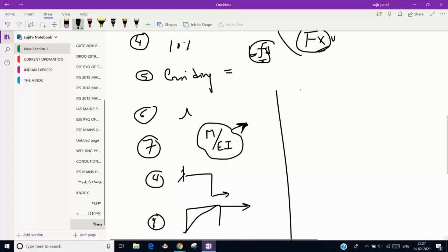Moving to the next question. There is one question on the application of friction: the angle theta is 30 degrees, and one block has a 900 Newton downward force and a 750 Newton horizontal force acting on it. We have to find the coefficient of friction to just prevent the block from sliding down.